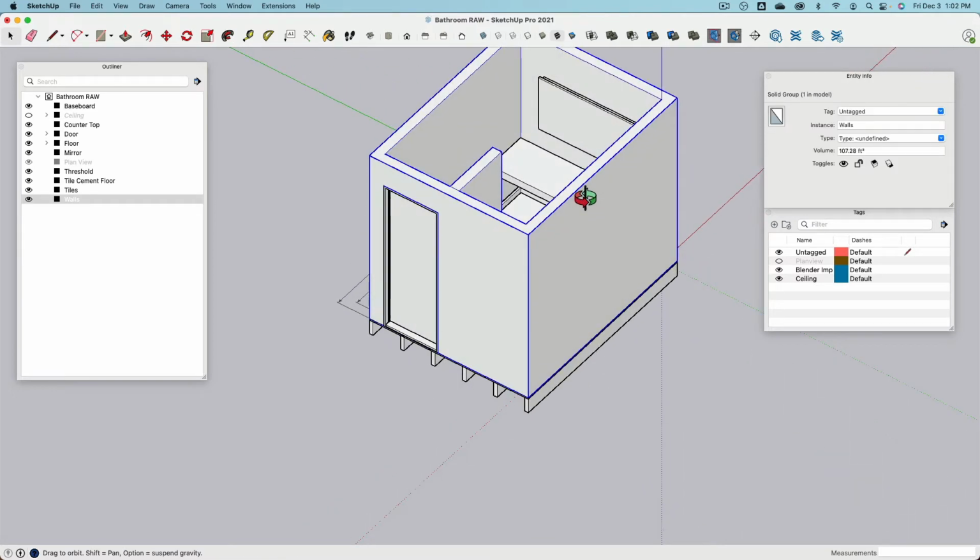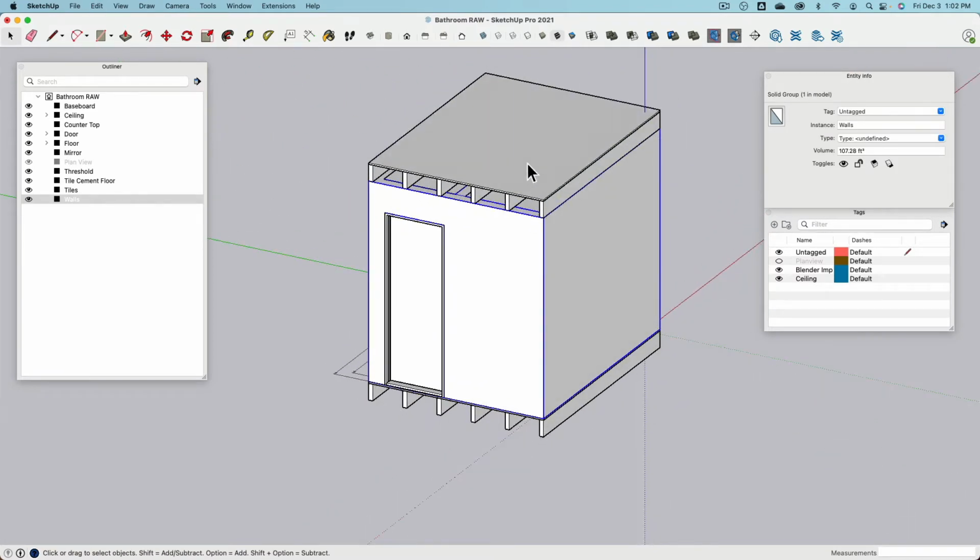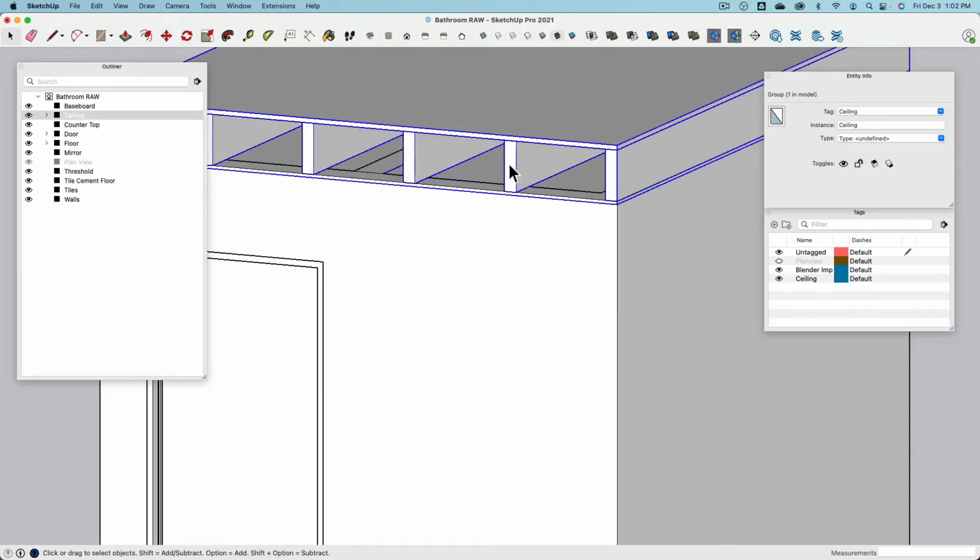Now there are the walls. And then we have the ceiling. The ceiling is pretty much the same. We have the joists which sit on the wood framing. The walls are basically representing the interior wood framing plus the drywall casing. We say 5 inches thickness. That's actually not even correct, because even when we buy 2x4, the wood isn't really 2x4 when measured. It's a pre-cut 2x4, and then they even it out so everything shrinks a little bit.